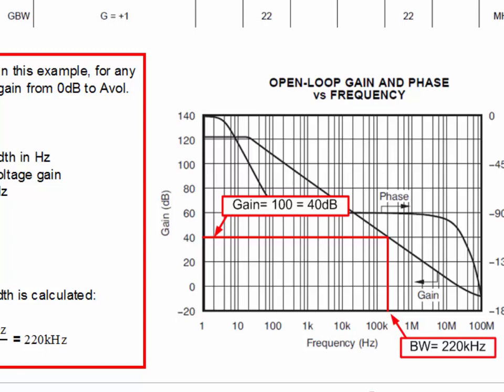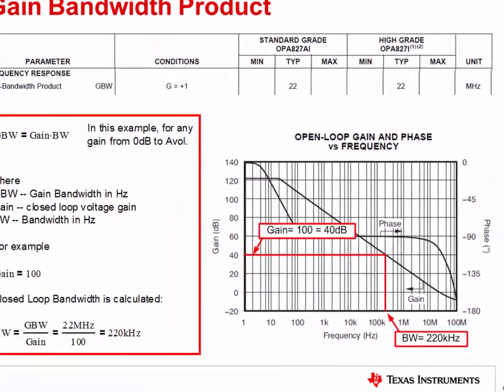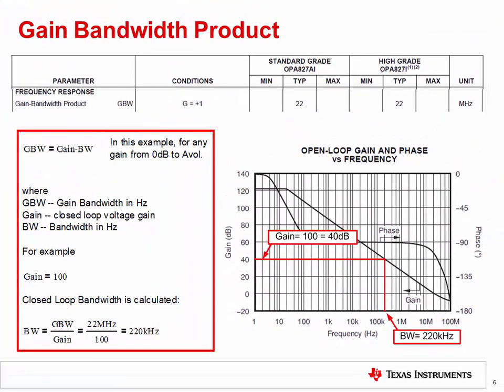While this is true for most op-amps, there are some that have a limited range where the gain bandwidth product is specified. Also, consider that the datasheet gives only the typical value for both the gain bandwidth product and AOL curve. Generally, you can expect a variation of as much as plus or minus 30% from this value at room temperature, and an additional error of plus or minus 30% over the specified temperature range. So it is always advisable to include margin in your design when considering amplifier bandwidth.